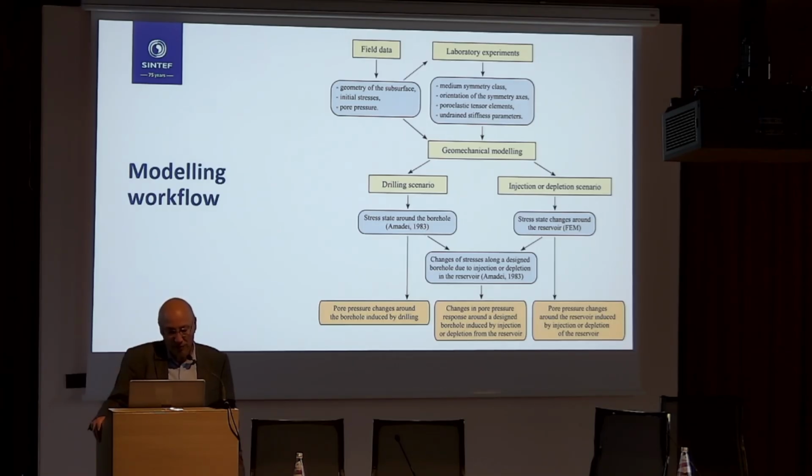Then you populate your geomechanical model, and then you look at your drilling scenario, the case of depletion, and what happens if you're injecting as well. And then you have all sorts of numerical analysis that can help you with complex geometry. And you can get several interesting things in the end: the pore pressure around the borehole induced by the drilling, the changes in pore pressure in response around the designed borehole, and the pore pressure changes around the reservoir induced by injection or depletion. Around the reservoir includes also the overburden.